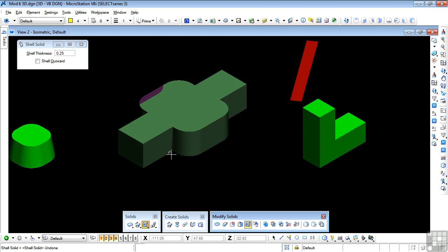I'm going to work on this solid, and I'd like you to draw that before you start yourself. Just use SmartLine to draw the top surface, but remember, just draw half of it and mirror it and then turn it into a closed shape, and then extrude it vertically downwards. Make sure though that you do not keep the profile, otherwise you'll find problems later on.